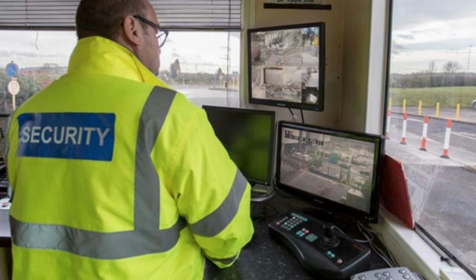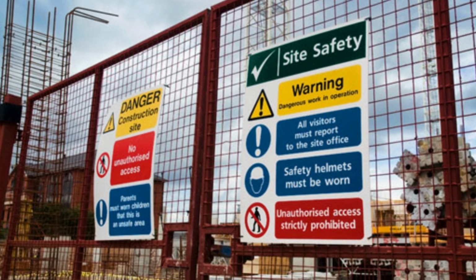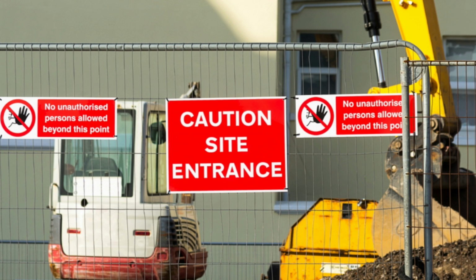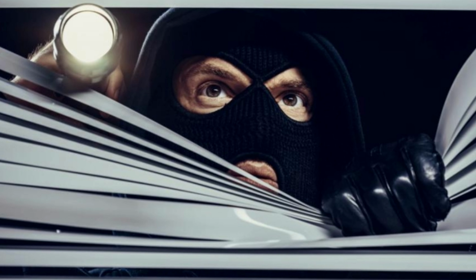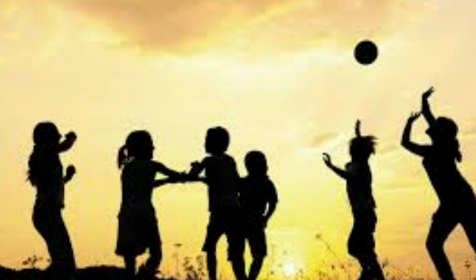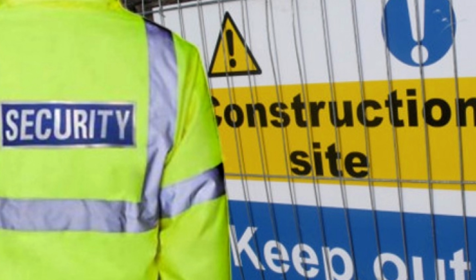Site security. Building sites and areas of maintenance and renovation are inherently dangerous places. They can also act as a lure for unauthorized visitors, such as members of the public taking shortcuts, a public right-of-way possibly going through the site, thieves entering to steal plant or equipment, children drawn by curiosity. Good site security is therefore important, especially when the site is in an urban area.